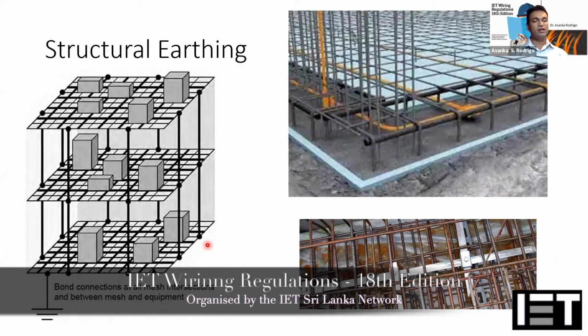That's why the standards recommend this type of equipotential bonding with surge protective devices, because surge protection is also mandatory. Just connecting them is not enough, but also because you have to maintain your services at the same potential as well. To maintain that, you need to have the surge protective devices. With that, then connect everything. You don't need to be afraid of connecting them. Connect all these steel frames, steel bars, everything, and even the foundation, and create equipotential bonding everywhere.